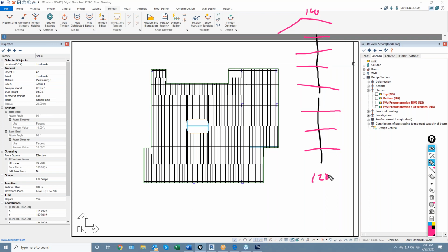The control that code checks this is set under display. That's set to 125 right now. This one would say no good, this one would say okay. And that's more of a mechanical check. In reality, if you go to FEM, that distribution of stress would be more uniform, and this might jump down to 145 and 145. So you just have to watch out what's going on with the tendons and the distribution of the cuts when you're using number of tendons.